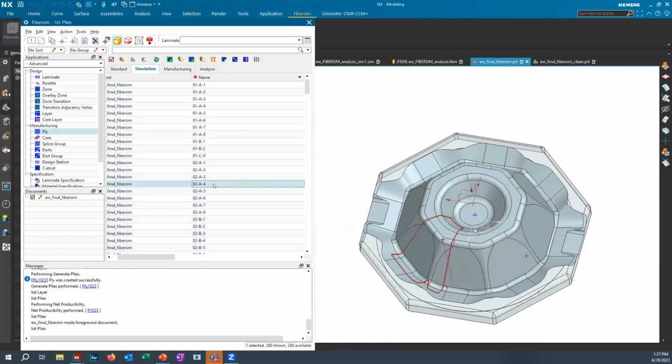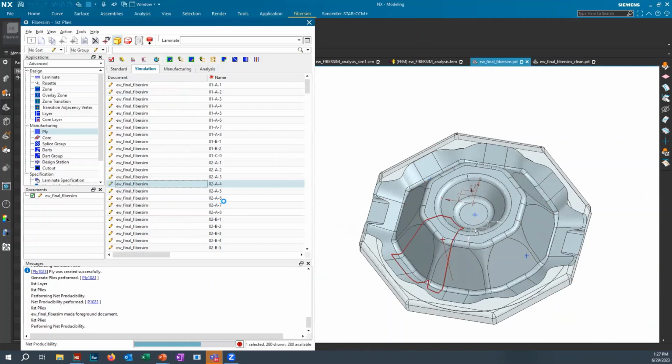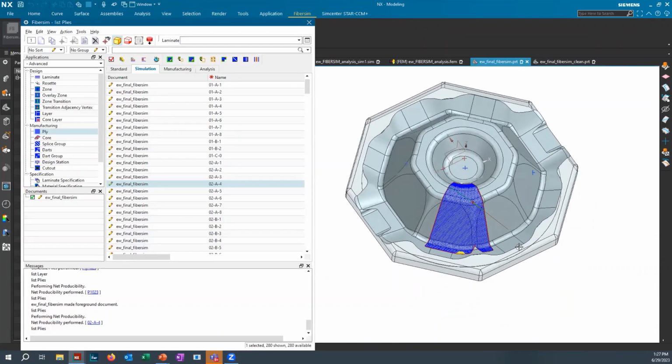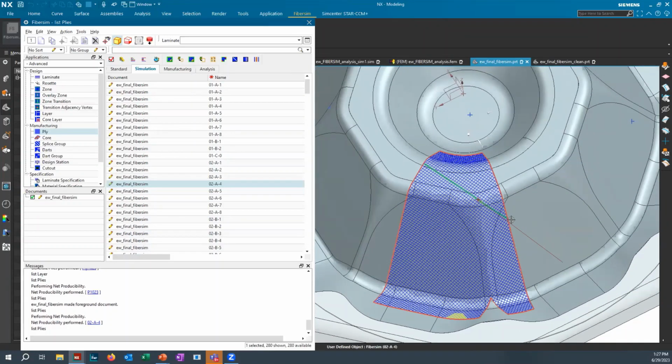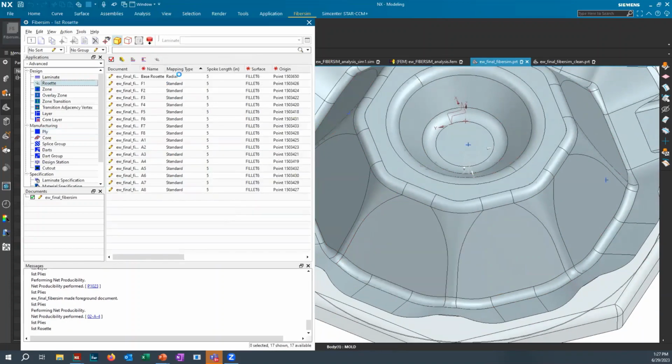Now, some of these parts ended up having to be darted quite a bit to ensure that we could actually manufacture this. Here, we're going to do producibility on one of these parts. One thing to note is we had specified during this design process that the designer wanted a radial rosette. So the idea is that we want the zero direction to propagate outward from here.